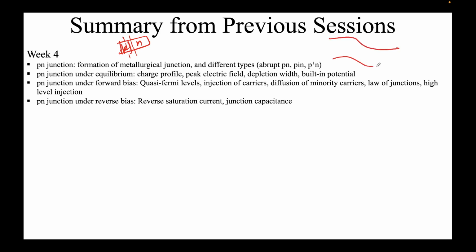That is the depletion region where no mobile charge carriers are there, and we saw the band diagram used to look something like this. This is the P side, this is the N side. This band bending will happen in the depletion region. Depletion region means there are no mobile charge carriers, but there will be negative charge here and positive here. Now, this is an abrupt p-n junction.